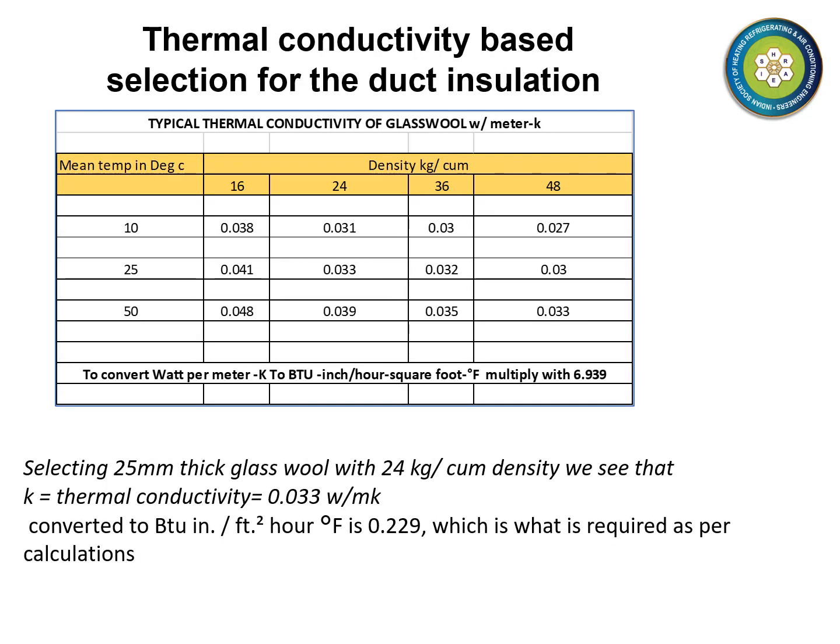If we decide to use glass wool as insulating material, 25 mm or 1 inch thick glass wool is adequate as shown on this slide.